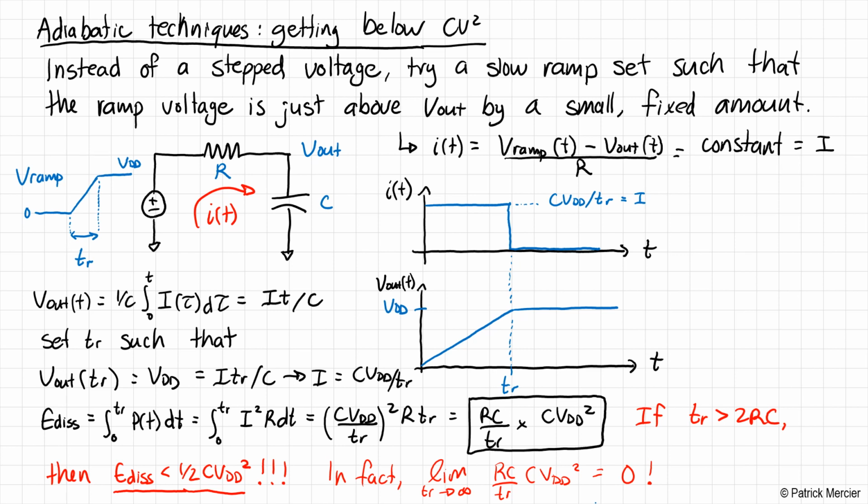This is a very attractive idea to a number of designers. You know, oh, I can build a whole digital system that consumes no power. Now, this is a curious possibility here. In practice, it turns out to be rather difficult to do this effectively without overhead in order to generate these ramps and so on. And then there's all sorts of interesting questions, like how do you build timing for adiabatic logic. Many researchers have tried this, and the conclusion is that it's really hard to build a truly adiabatic logic family that has significantly improved performance over voltage-scaled static complementary CMOS.